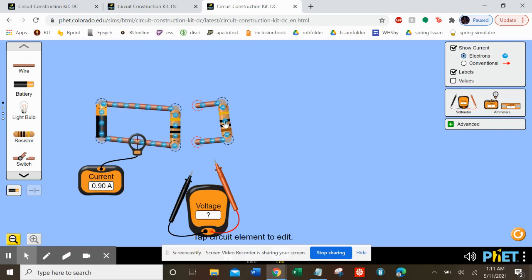I don't care if the hallway is really, really big and open, or if it has a huge resistance. If my hallway is super, super thin, super small, only one person can fit through it. If I'm adding a second hallway, more people can walk through it. So even if it's a big resistance, once I add this resistor in parallel, you'll see this current will go up, no matter how big that resistance was.